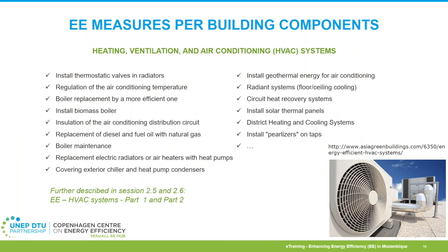As for the HVAC systems, possible improvement measures proposed are: install thermostatic valves in radiators if radiators are in place, regulation of the air conditioning temperature, boiler replacement by a more efficient one, install a biomass boiler, installation of the air conditioning distribution circuit, replacement of diesel and fuel oil with natural gas, for instance, maintenance of the boiler or any other equipment, covering